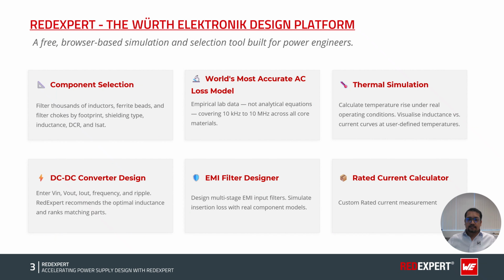Second, DC-DC converter design. You just enter your input voltage, output voltage, load current, and switching frequency, and REDEXPERT recommends the optimal inductance and ranks all matching components for your exact operating point for that DC-DC converter. Third, you can also design multi-stage EMI input filters and simulate insertion loss using real measured component models, not idealized curves only. Fourth, thermal simulation.